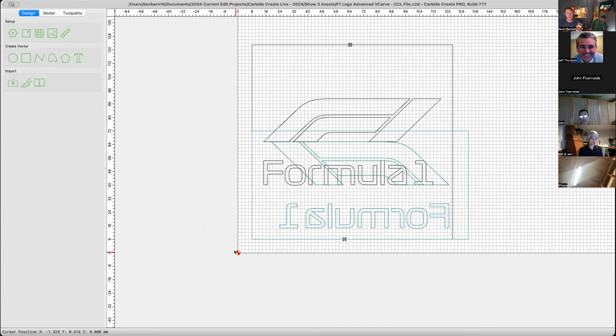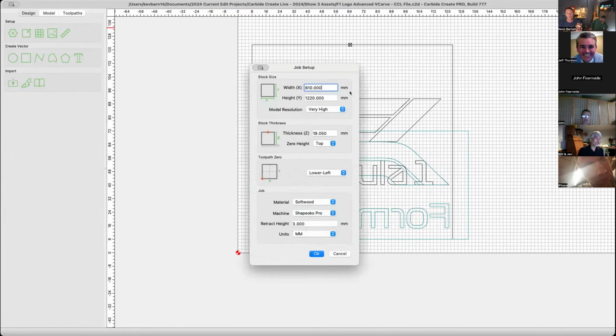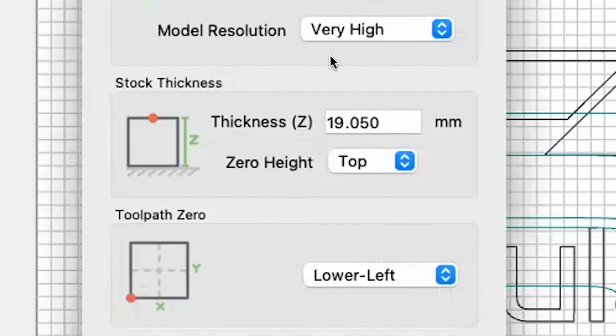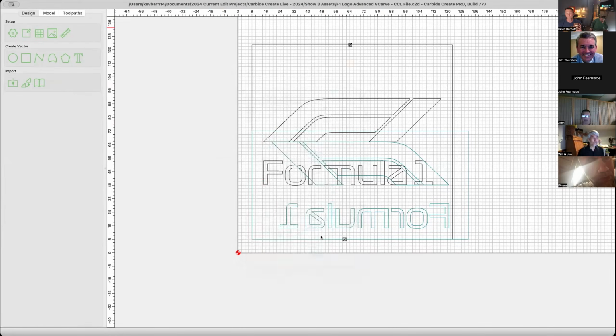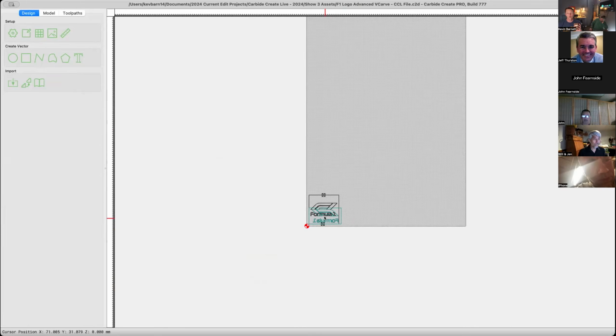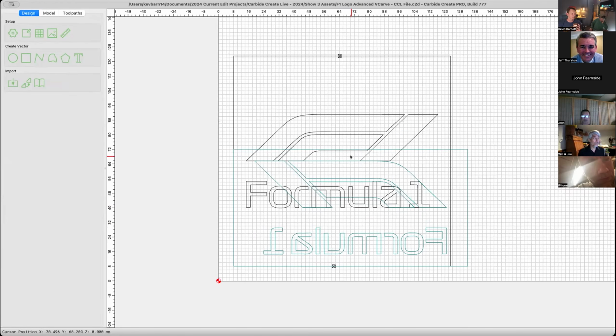But then I can start my cut from the same location also. I can simply replace my stock, because you're going to do one side out of walnut, one side out of maple, and I can go to that same XY point. I can set up a little known location on my machine. I can use the same 0 point, as long as I change the Z measurement or the stock thickness of my material, because it's probably going to be different. I cut one side, cut the other side. Questions so far on utilizing layers?